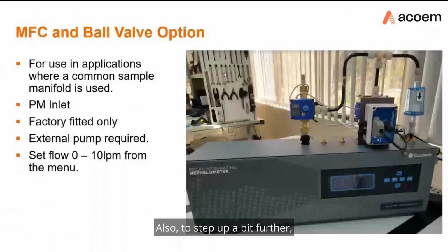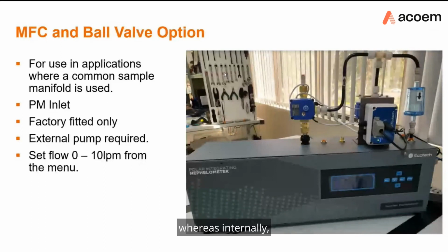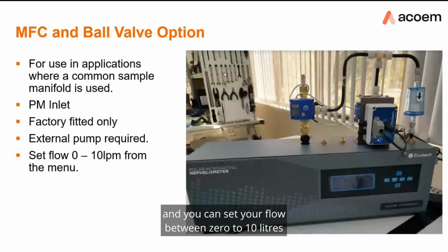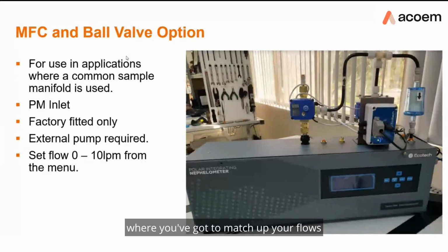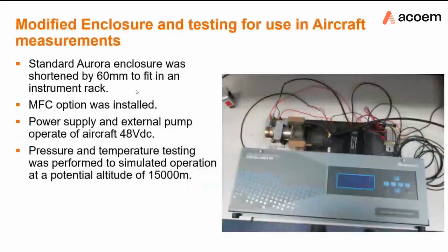Also, to step up a bit further, you could have the MFC and ball valve option. This is basically the same as the ball valve option, whereas internally there's a mass flow controller installed, which is programmed and controlled by the Aurora Nephelometer itself through the front menu. And you can set your flow between 0 and 10 litres, or you can have a 0 to 20 litre mass flow if you desire. This option can only be factory fitted, but it's very good for situations where you've got to match up your flows with other instruments where you're using a common inlet in your system.